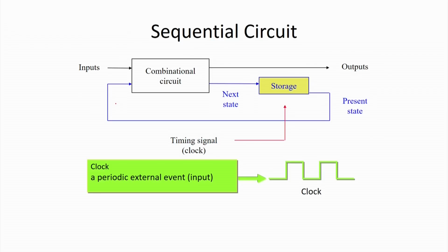Depending on input, we are going to get the output, and some of the output is going to act as an input for the next time. So, those outputs we need to retain, and this is some sort of storage element. This storage, whatever we have stored or retained, will come as an input to the circuit, and the next output will depend on the current input as well as the previous output.